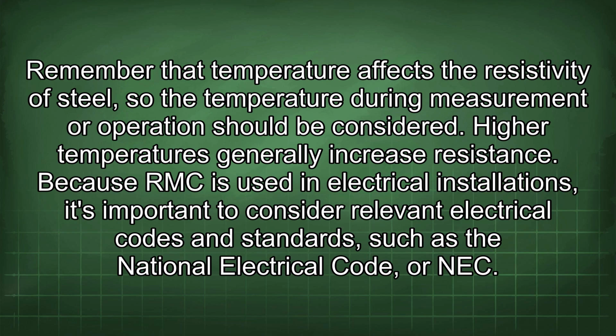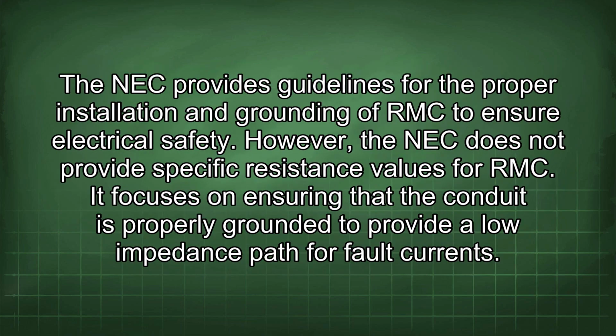Because RMC is used in electrical installations, it's important to consider relevant electrical codes and standards such as the National Electrical Code, or NEC. The NEC provides guidelines for the proper installation and grounding of RMC to ensure electrical safety. However, the NEC does not provide specific resistance values for RMC. It focuses on ensuring that the conduit is properly grounded to provide a low impedance path for fault currents.